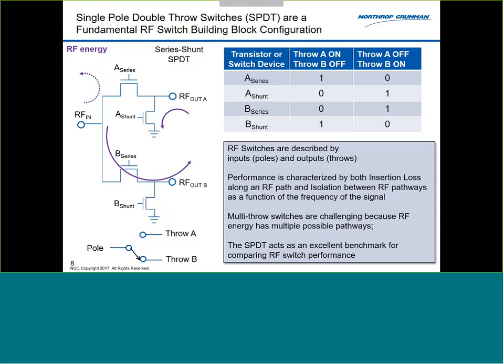You're absolutely right. All the RF design comes down to how I can trap the RF energy so it goes where I want it to go. You have to worry about reflections as well as isolation. I like this topology in particular because when you look at the insertion loss, it's very telling, because in this particular topology, things like isolation and reflection problems also show up as insertion loss.